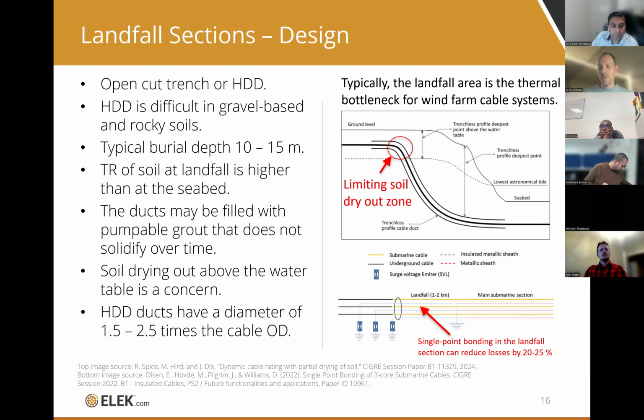For HDD ducts, typically it's recommended to have a diameter of those ducts of between 1.5 to 2.5 times the diameter of the cable, which is quite large. 200 millimeters internal diameter or larger.